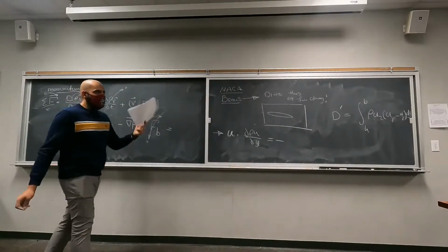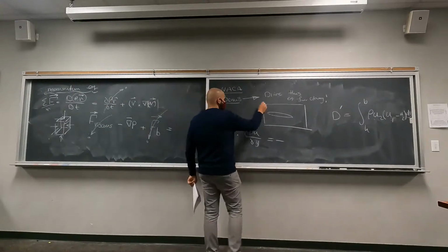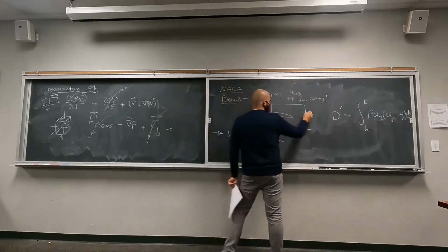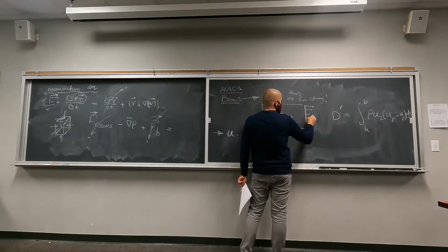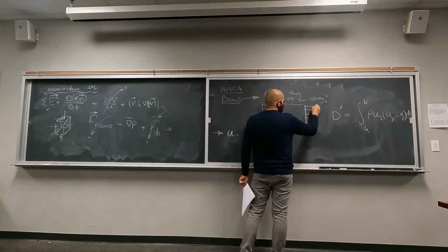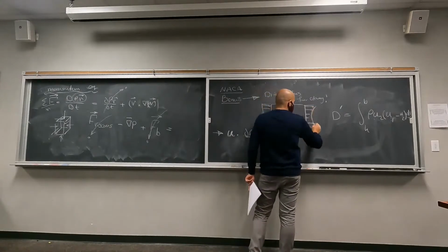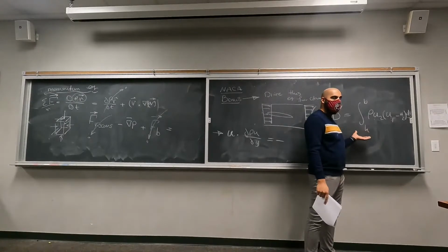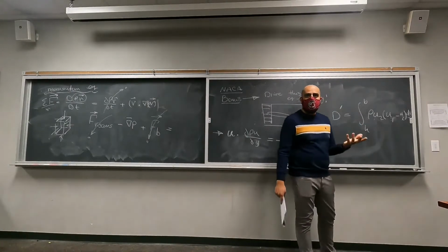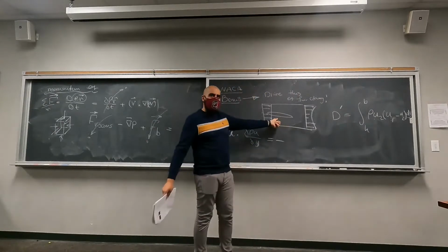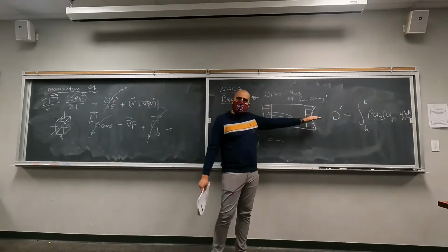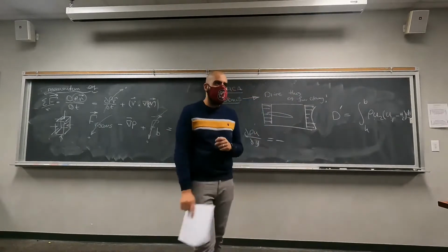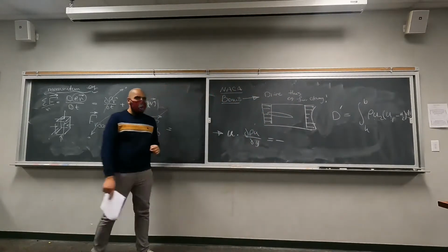So what does this equation tell us is that as long as you can get the velocity distribution here, and you can get the velocity distribution here, this equation, this integral, is going to give you the total momentum that has been lost to this airfoil in this direction, which is the drag force. This is the definition of the drag force. Any questions so far?